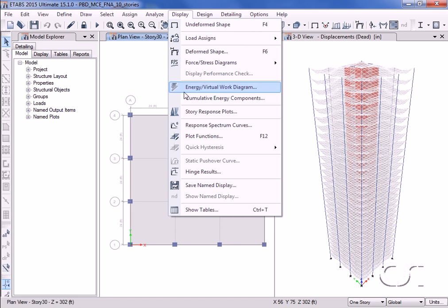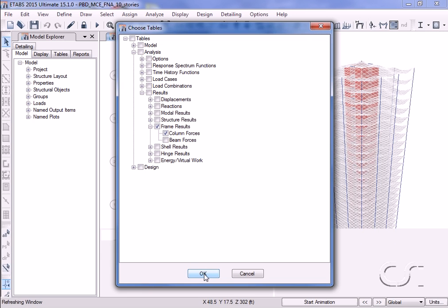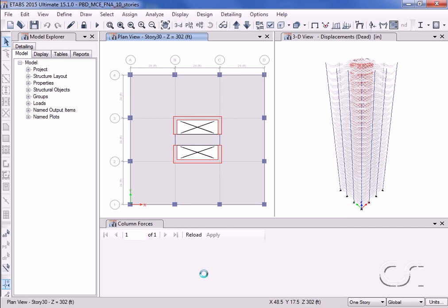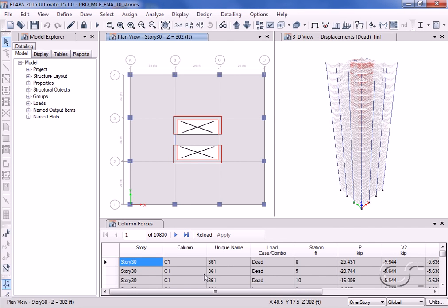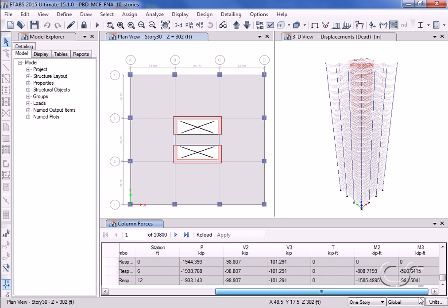In addition to looking at the behavior of the deformation-controlled elements, the forces in the force-controlled elements, such as the columns in this model, should also be reviewed to ensure that they are not undergoing significant nonlinear behavior. For a maximum considered earthquake analysis, the critical action in the columns might be limited to the traditional nominal value times some multiplier, for example 1.5, based on the fact that the expected strength is higher than the nominal value.